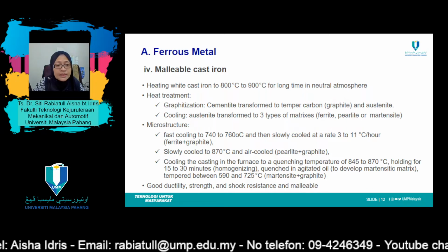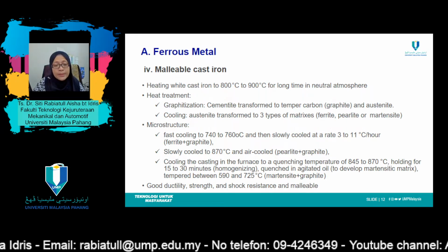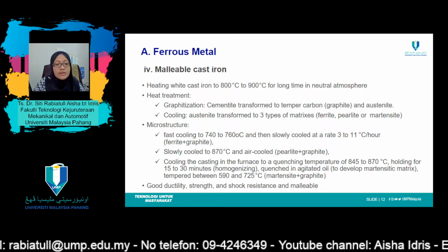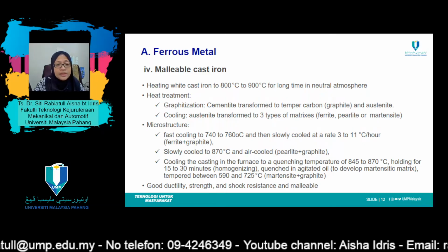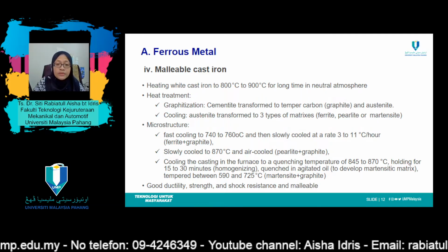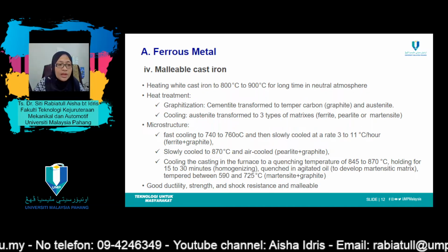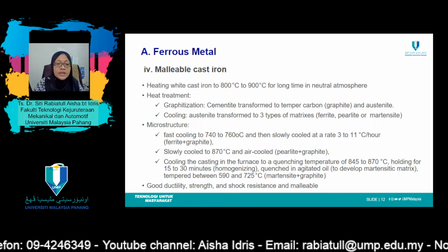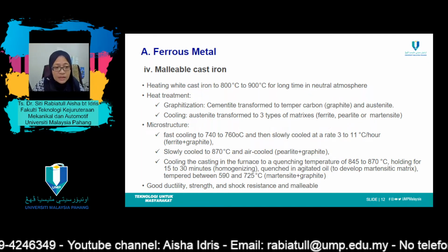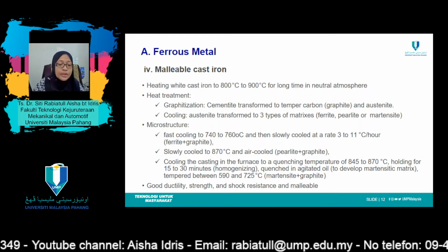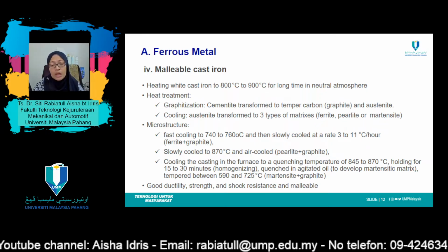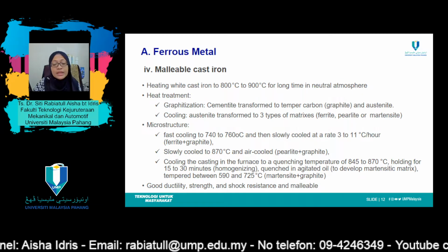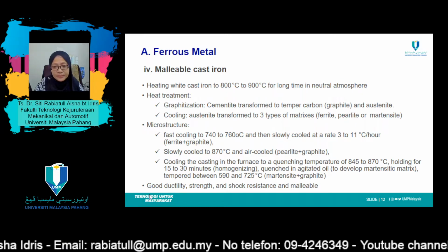appreciable ductility or malleability. Representative applications include connecting rods, transmission gears, different cases for the automotive industry, and also flanges, pipe fittings, valves, marine, and other heavy-duty services. Grey and ductile cast irons are produced in approximately the same amount. However, white and malleable cast irons are produced in smaller quantities.